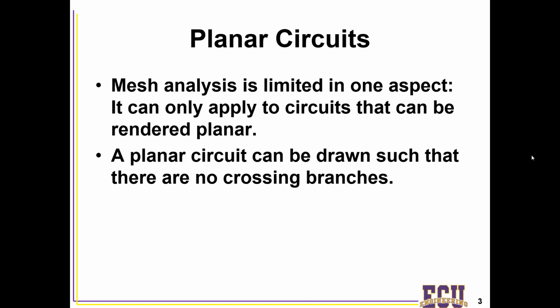In order for mesh analysis to work, the circuit being analyzed has to be planar. That means if you can draw the circuit such that all of the components are in a single plane, that is a planar circuit. But if you have a component that is connected in such a way that it would always cross over another branch, then that is not a planar circuit.